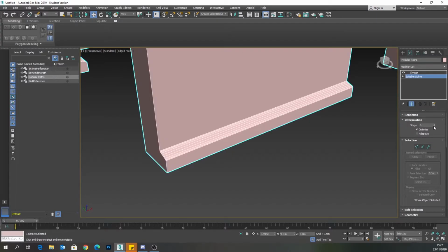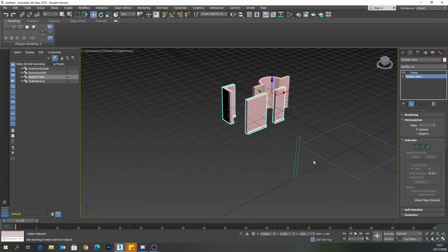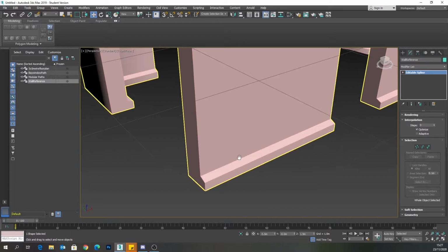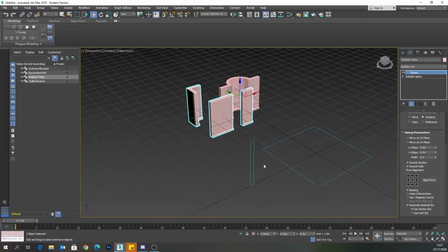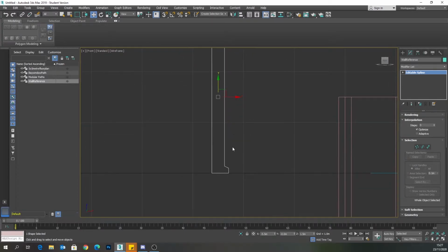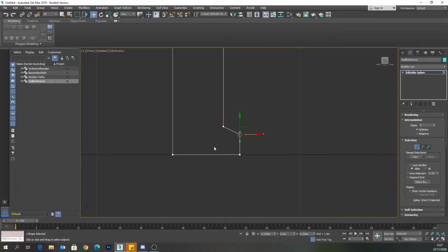If we lower the interpolation on these, when we have corners, that will change on there. But if we do it on the reference shape, like we've selected here, you can see that it will lower the amount that's going throughout. So interpolation is like how rounded some of these edges are going to be. Usually you'll get away with a setting around 0 to 2 for in-games, and make sure that optimize is selected underneath.